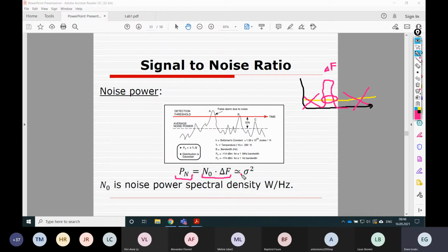Or it can be expressed in simulations or calculations with noise variance. Roughly it's the same; it's not like 2 or 3 times bigger, it's just this variance. This noise can also be calculated for a thermal process according to this formula, where k is the Boltzmann constant from physics, and capital T is the temperature, basically the temperature of the element, of the receiver, of the antenna, of the component, expressed in Kelvin.